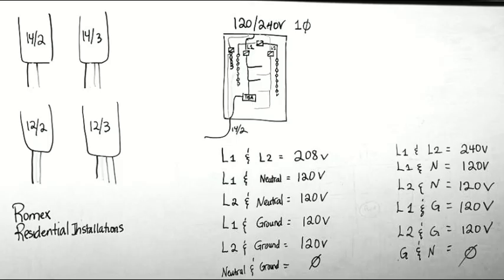So just because I can put a bunch of load into a circuit, that doesn't mean that I'm gonna install it. Because as I become not only a person that runs wires and installs boxes, I evolve into a person that understands electricity, and also I become a designer, right? You understand circuits, and you say, okay, I know I can put 100 lights here, but I'm gonna stagger them, so if one of the circuits fails for any reason, the customer still has lights as an emergency around their house.